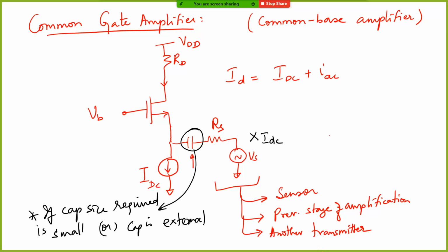It's not possible. Okay, typical values of capacitance, see, using MIM and MOM, it is typically limited to maybe a few picofarads at the maximum, okay, or typically less than 1 picofarad is what is used. And for other requirements where you need higher capacitances, probably tens of picofarad can be realized using MOS capacitance.